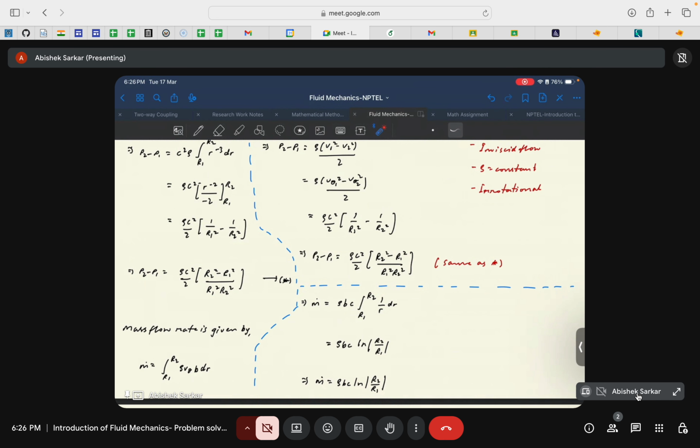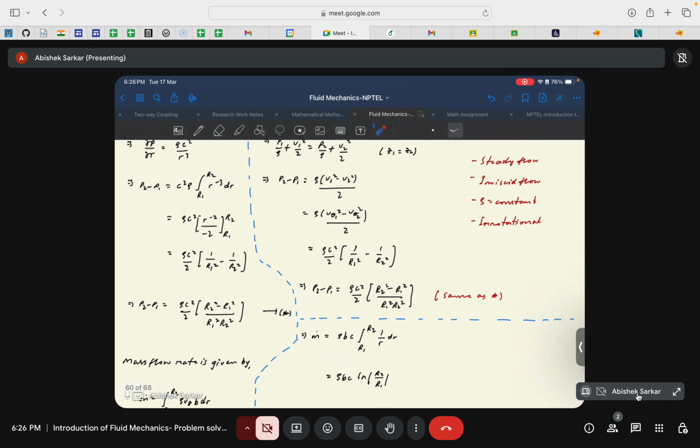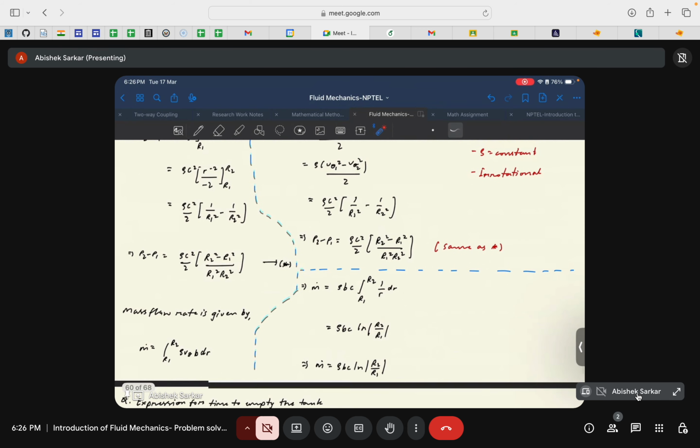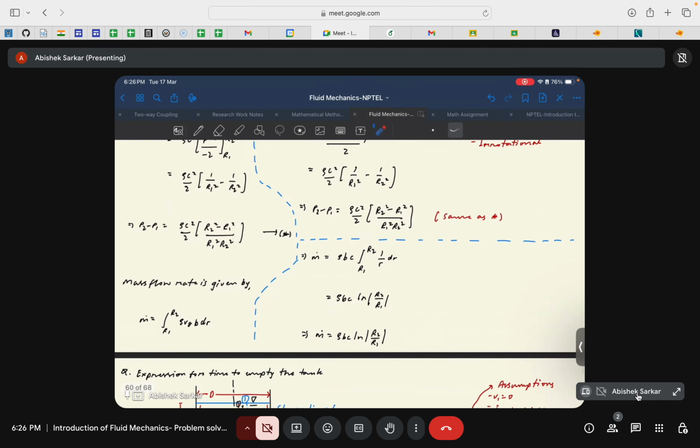But now, by understanding that these 4 conditions are inherently satisfied in this flow, you do not even need to look into any specific equation of motion, be it Navier-Stokes or Euler. If these 4 conditions are satisfied, then you can easily apply Bernoulli's equation between any 2 points and find the pressure difference. I personally felt that this was a very profound and important result.